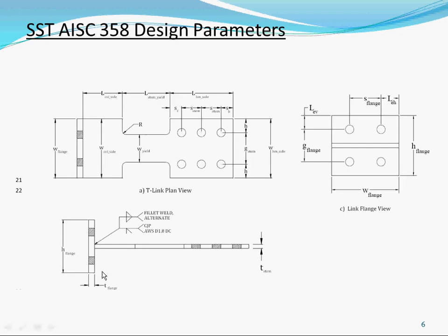Because we're fabricating it, we don't want to change too many thicknesses of steel, because when you stock it, you want to limit it to certain shapes, and when you buy a lot of them and keep using them, it's a little cheaper instead of having to change. And our guys in the shop, you don't want to confuse them either. Simplify it as much as possible, so they don't make mistakes in the shop. But when we provide the design, we give dimensions on all of them. So the fabricators, when they see this, can fabricate it.